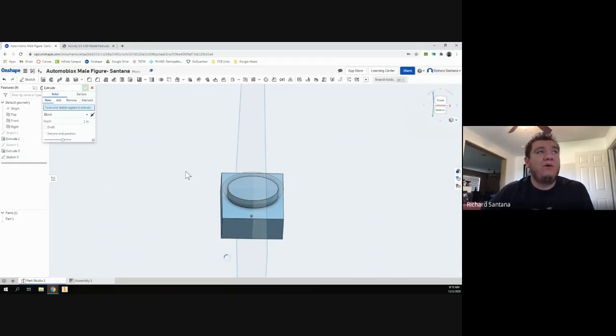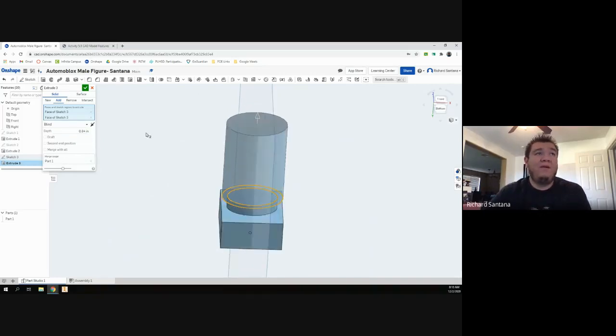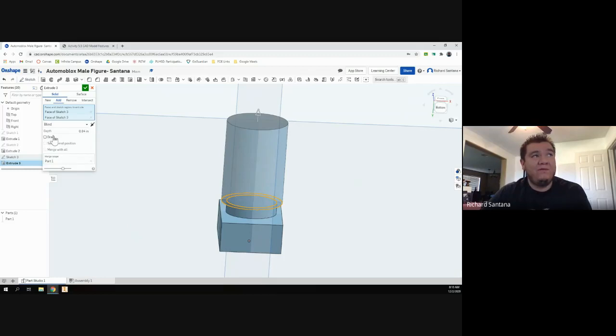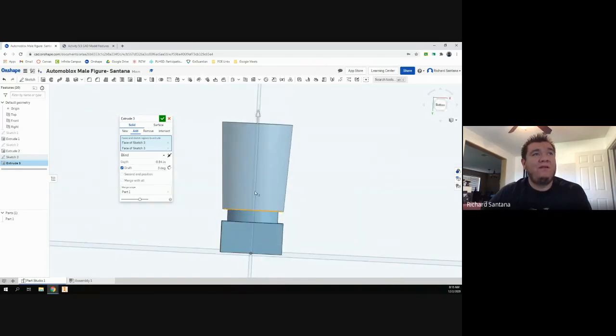And I'm going to extrude both the inside and the outside. And we said it's going to be 0.84. Now, before you go around clicking OK, we have to add a draft, and you'll see that button right there, draft. All right. You'll see that by default, the draft is 3 degrees. And so all it did is it went up 0.84 like normally, and it added 3 degrees in every direction. We want to change that to 4. And you'll see what happens.